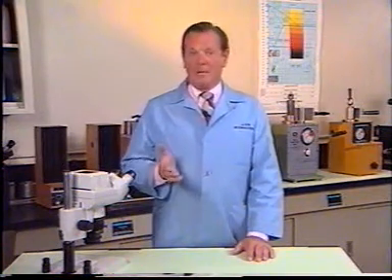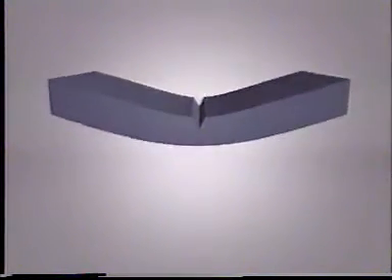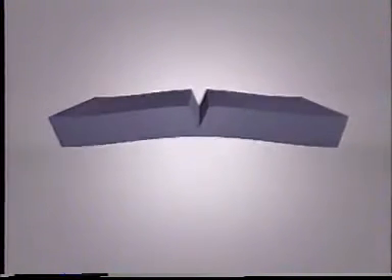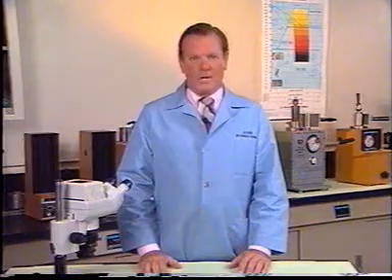In brittle materials, they may also be caused by compressive stresses. For the failure analyst, visualizing the applied stress can be fairly simple and automatic. For example, if a straight flat bar is loaded at the ends with a fulcrum at the center, it seems almost obvious that fracture will occur somewhere on the upper surface, somewhere on the convex side of the bar in tension. The lower surface is squeezed in compression and becomes concave. It is the relationship between the applied stress and the inherent strength of the material that determines the location where any type of fracture will originate.